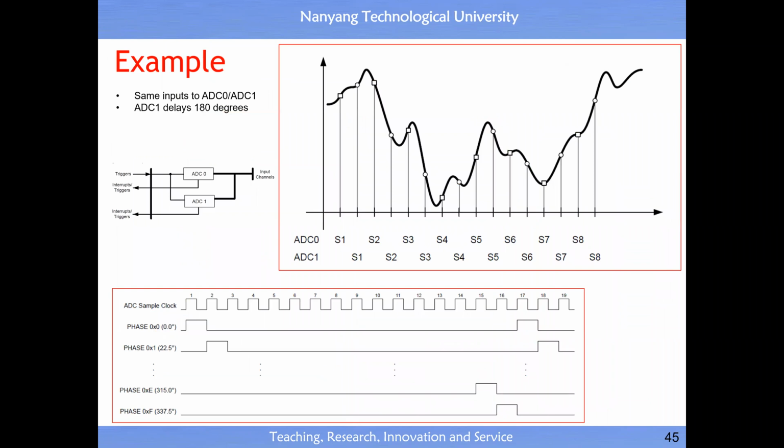Another thing is, since you have 2 quantization devices, they allow you to offset. That means they do not start at the same time. They have an offset. Offset means, in electronic language, a degree difference, a phase shift. So this allows you to make these 2 quantization devices take input from the same sensor, then double the resolution.